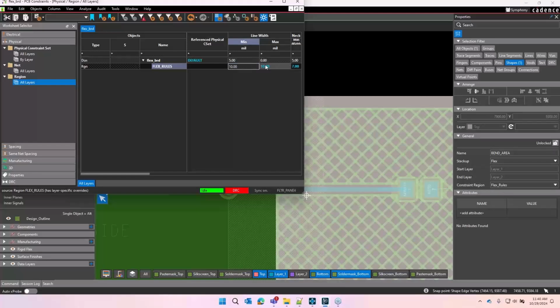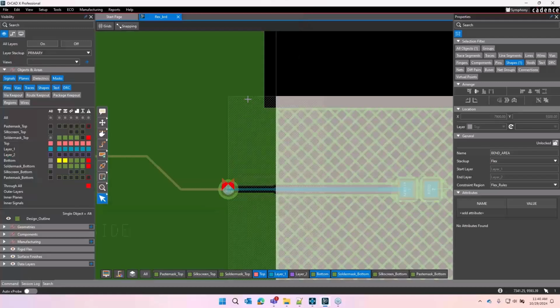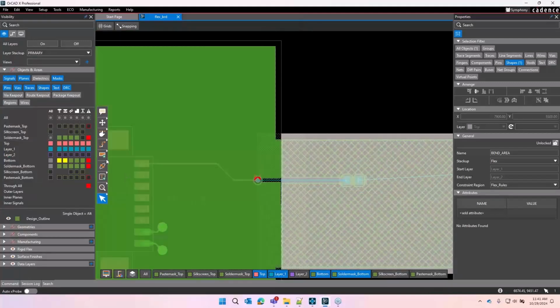And you can see that I have some different widths associated with this one as opposed to the default board. And this is where Lauren was saying you're going to be talking with your board manufacturer. You're going to be having those early conversations with them to determine what some of these rules should be. And then you can just enter them in here. There are calculators that you can use to figure out some of these numbers, but the recommendation would be to talk to your board house, because they're going to have probably a better understanding of their specific process and what the impedances are ultimately going to end up like. And if you want to match those impedances, they'll tell you which widths and spacings you're going to need to make those work. So that's where you can enter that flex rule.